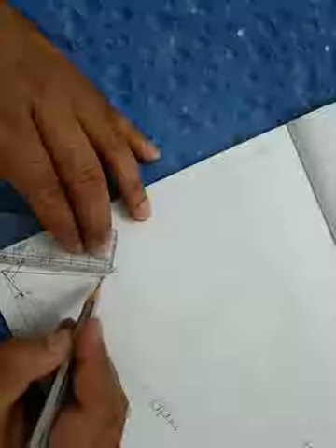If we measure it, it is 6 centimeter long. So OP is 6 centimeter. So total value of the line current is 6 into 5 is the scale, is 30 ampere, and phi is 30 degree. By measurement we measure it.